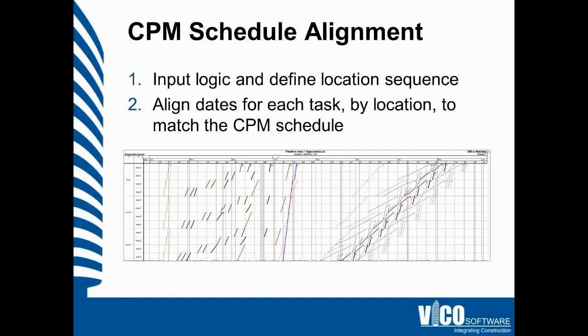We have linked those models and their takeoff items to a cost planner database, which we're using to pick apart the quantities and assign to individual activity line items that will be used to load the schedule. And then we've mapped those line items to the uniform task list that we have pulled from the CPM schedule. And at this point, we can move into the schedule planner environment